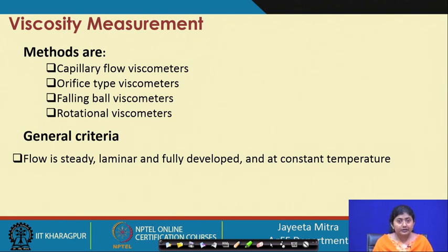We know that temperature has a significant effect on viscosity. In gases, we find that with increase in temperature viscosity increases. However, in the case of a liquid sample, we have found that with increase in temperature viscosity decreases. Although there is some effect of pressure as well, under normal pressure this is the phenomenon. That is why we need to follow this general criteria for measuring the viscosity.